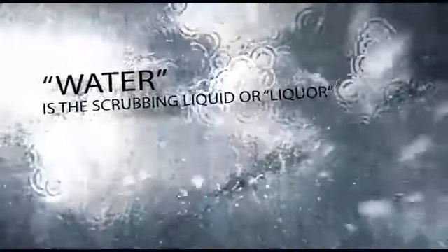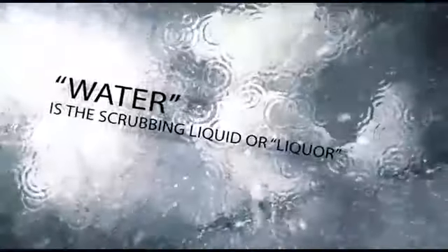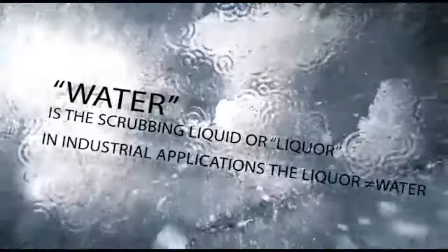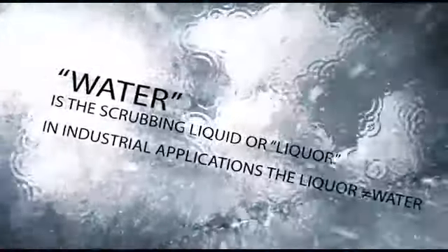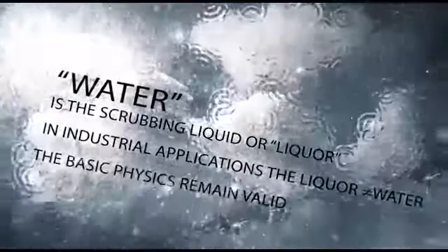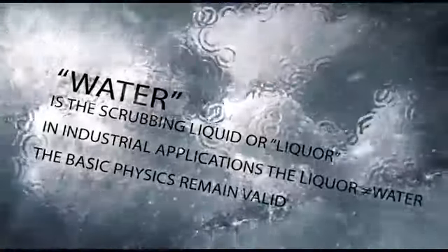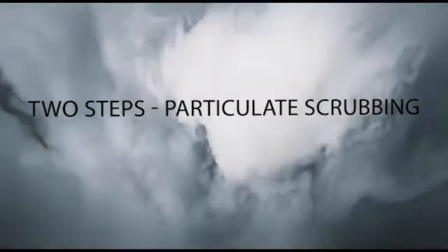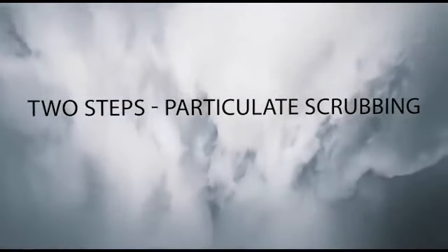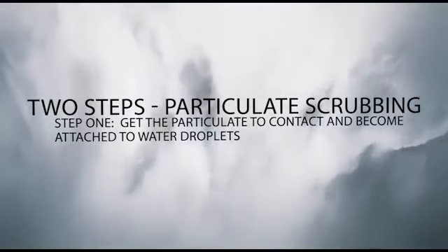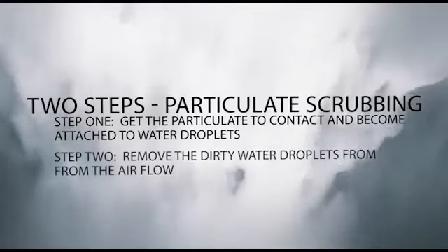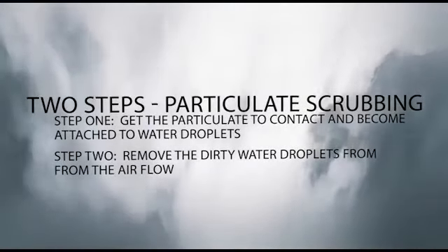The term water in this presentation is used to describe the scrubbing liquor or liquid. In many industrial applications, something besides water may be used, but for this purpose, we're going to just use the word water to describe whatever our scrubbing liquid is. There are only two real steps in particulate scrubbing. The first step is to get the particulate to contact and become attached to water droplets. The second step is to remove the dirty water droplets from the airflow.